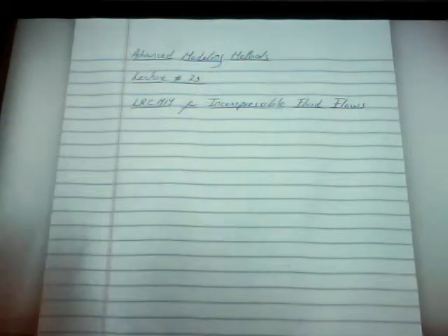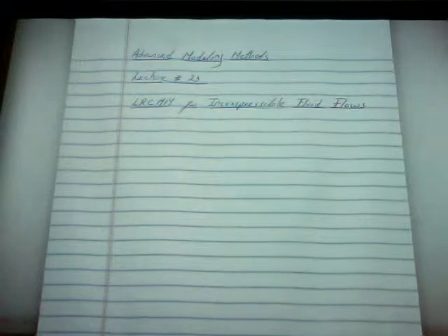So we're talking about incompressible flows, okay? That doesn't mean that we're only dealing with incompressible fluids. Remember that one thing is an incompressible fluid and another thing is an incompressible flow. An incompressible fluid is water, for example, okay? And an incompressible fluid will always flow incompressibly. Okay, you cannot flow water in compressible mode. However, you can take a compressible fluid, such as air, for example, and make it flow incompressibly. Okay, depending on some conditions.